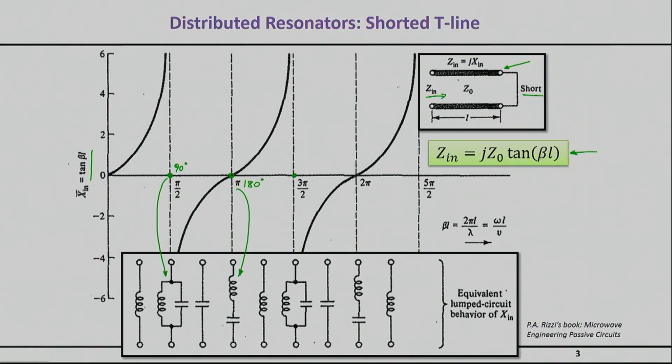Notice, by the way, something else that this graph shows us, which we have also seen before: when the frequency is pretty low, meaning when you're here, way below resonance, this is a shorted transmission line. Let me say it again, it is a shorted transmission line, which is basically equivalent to j omega L, approximately, an inductor. And we've actually talked about how you can implement inductors with short transmission lines.